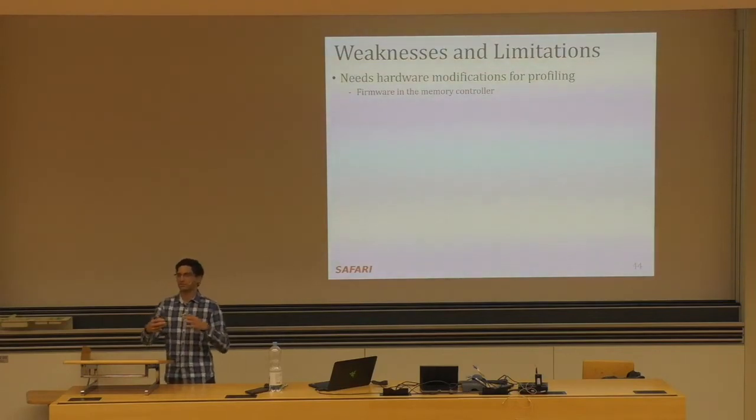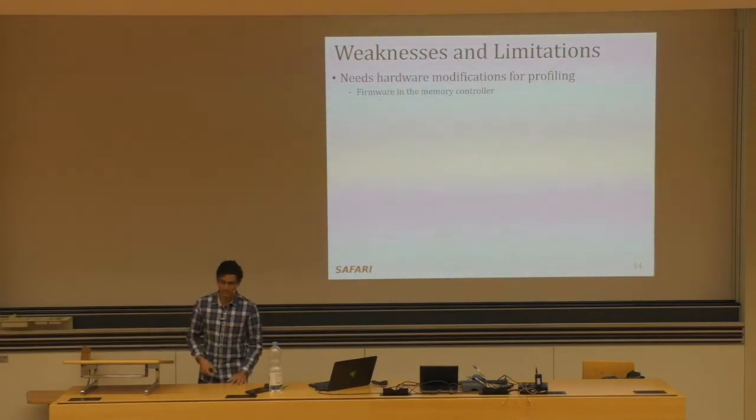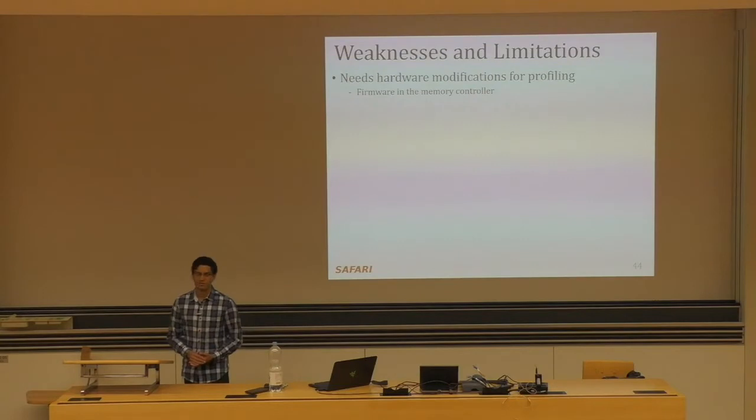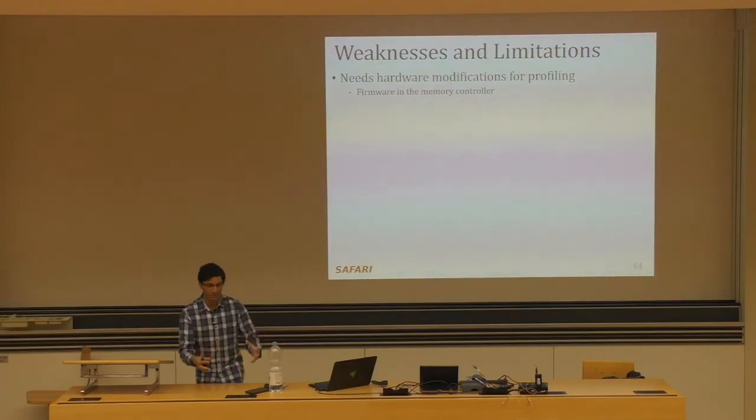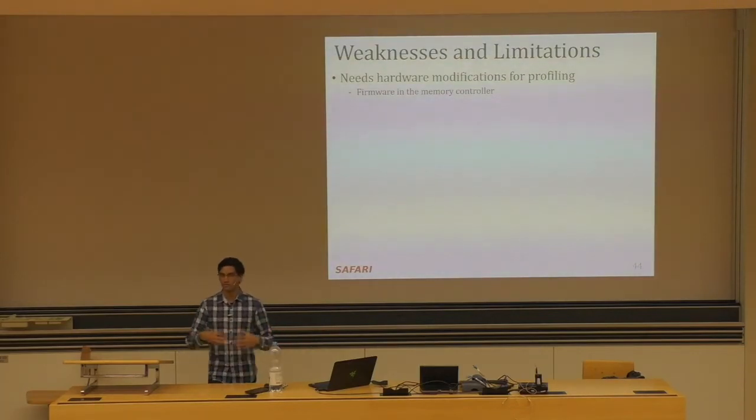And a rank, if you remember, is the level right below a channel. And so it's a huge region of DRAM, right? And so we have to change the refresh interval for this entire region at once, or not at all. And so when we're profiling, we have to somehow save that data that's already written there, and then we need to do our profiling, and then we need to copy the data back. It's a very extensive process, and it requires some sort of hardware support.